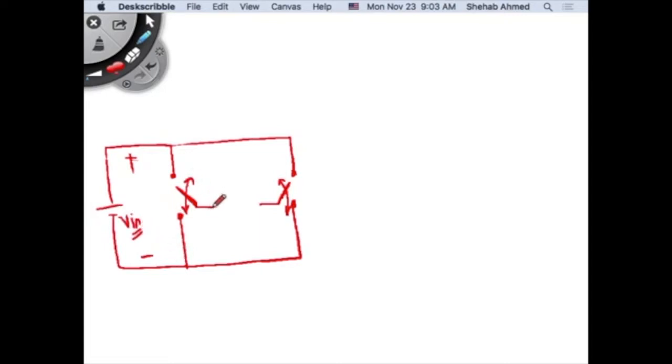And at the output, I always had in the buck, or the boost, or the buck boost, the switch current going through an inductor. And it's the same here. I can draw this as half the inductor here, half the inductor here. They're in series anyway. And then this is my load for my inverter.